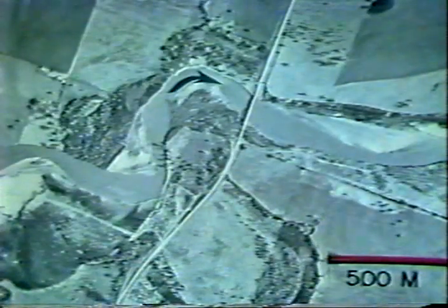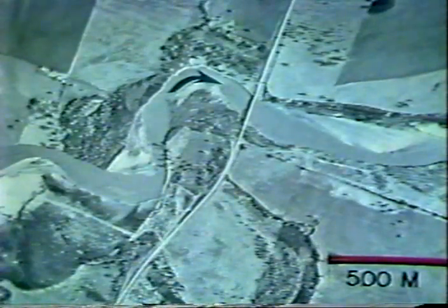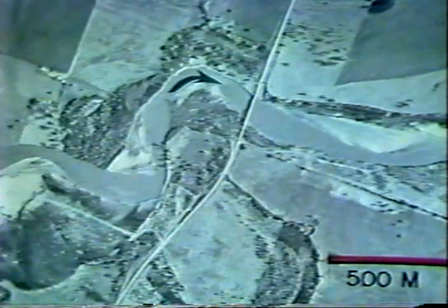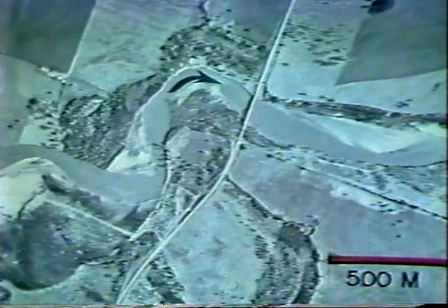The Washita River near Davis, Oklahoma, is a wide-bend point-bar stream having a rapid rate of lateral migration. Flow control and bank protection measures are needed to maintain a stable alignment at the bridge. When a new bridge was built at this site, a spur dike, shown at the right, rip-rapped banks, and short rock spurs were used as countermeasures.